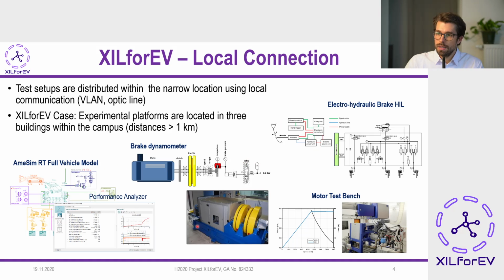These test benches, meaning a real-time full vehicle model running on a real-time PC, a brake dynamometer, an electro-hydraulic brake, and also a motor test bench, are connected through a virtual local area network that works within the university network. We experience delays between 2 and 5 milliseconds within this test environment.